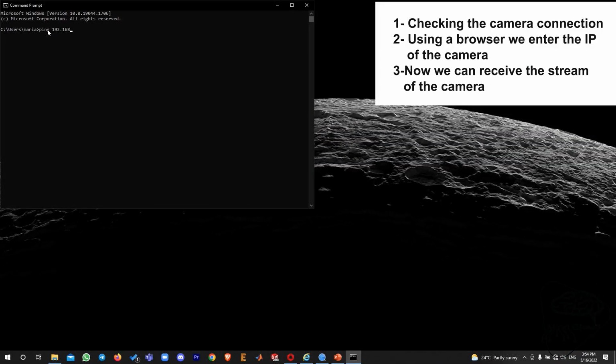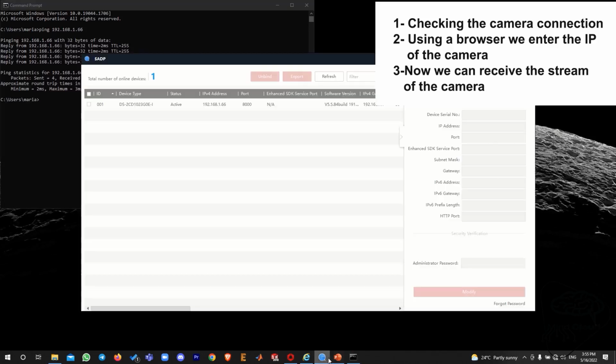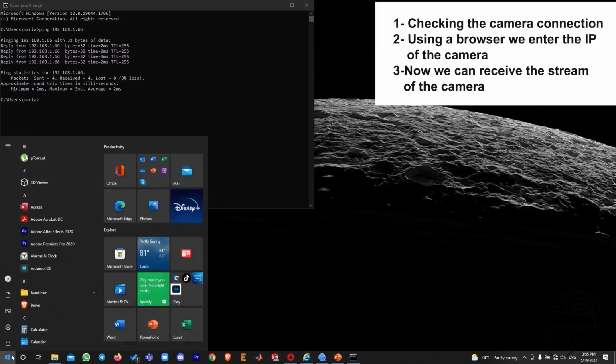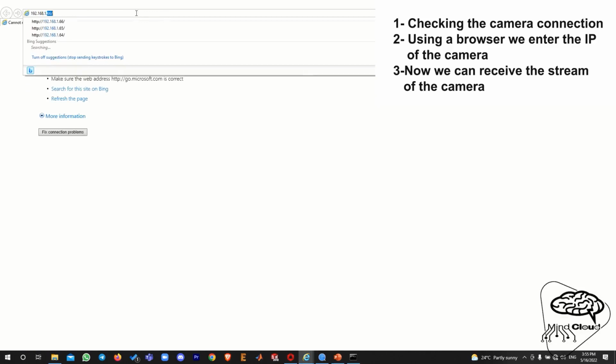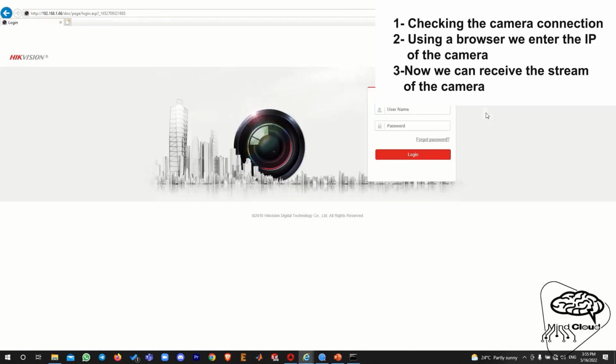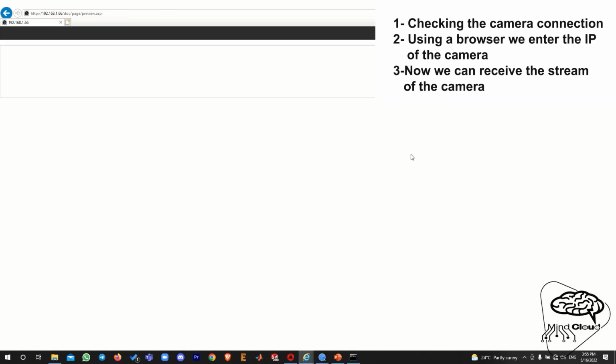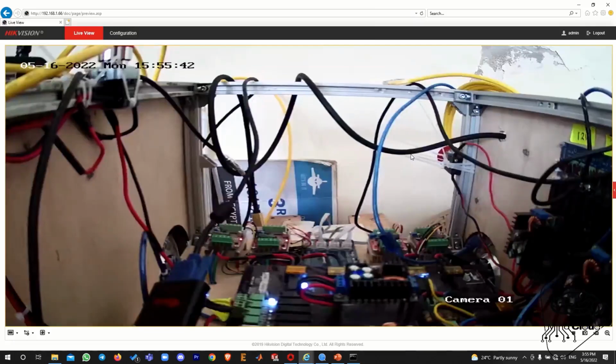The communication system is distributed between the control room and the rover. In the control room, we will have an omnidirectional antenna operating at 2.2 GHz and assigned to it a static IP. The antenna will be connected to the visualization laptops wired and connected to the router wireless. On the rover, we will have a router connected to the IP camera wired. The stream of the IP camera will be received on the visualization laptops using UDP protocol.